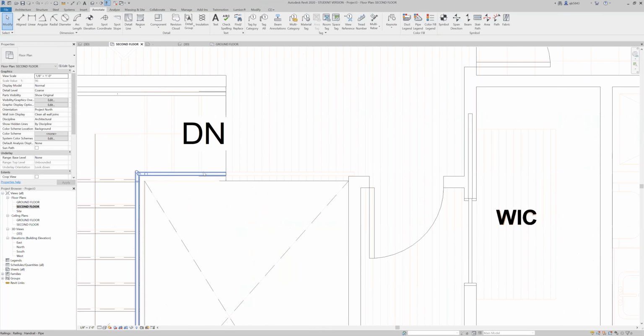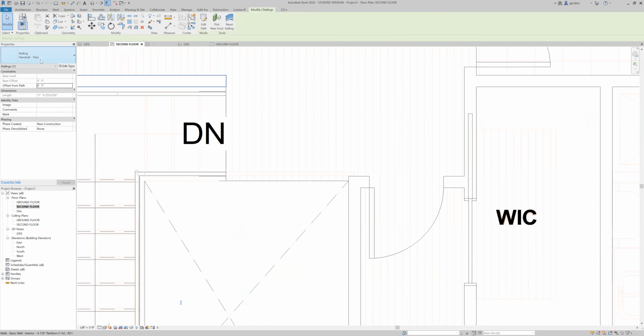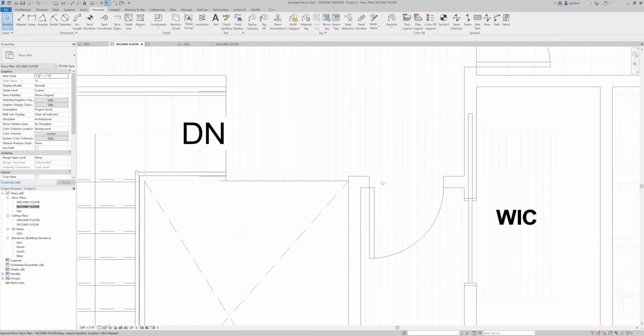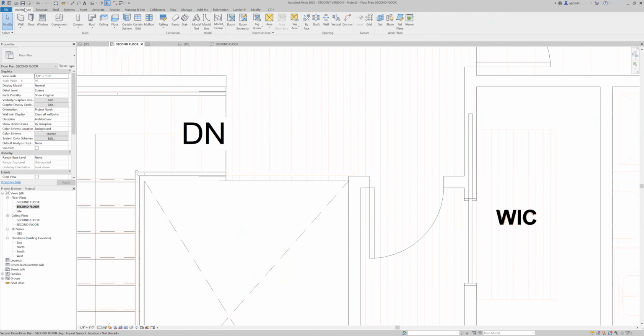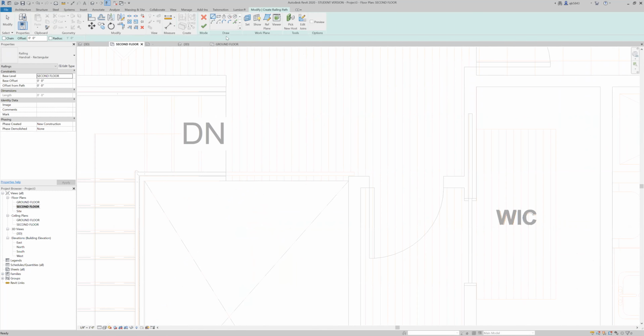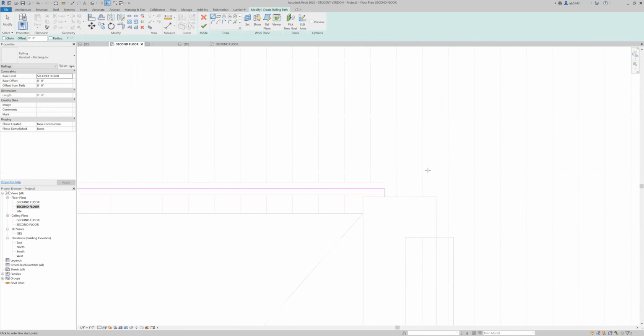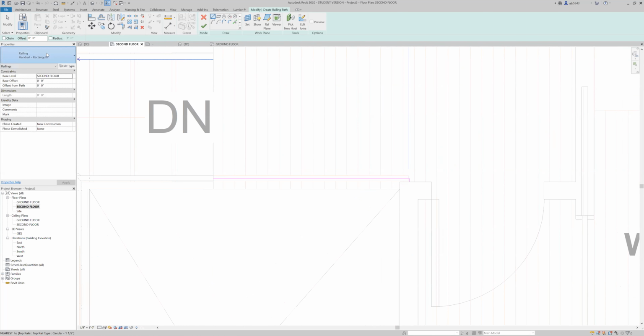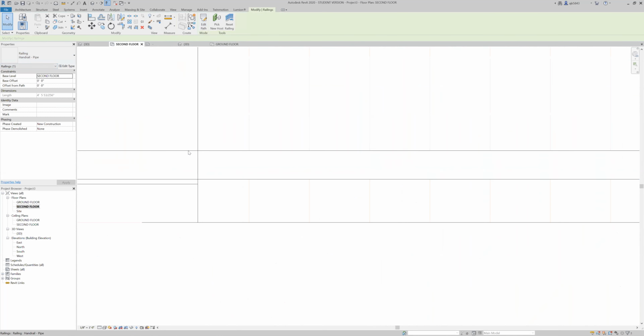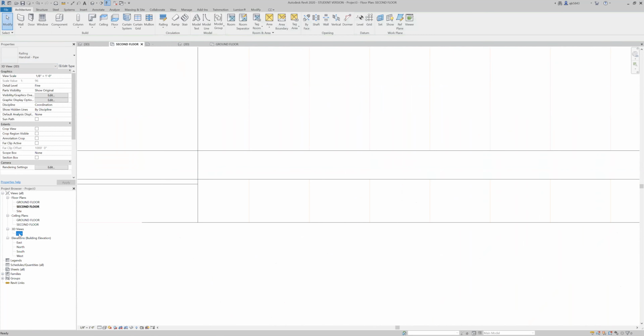And then probably the last thing right here is to continue this pipe handrail. So this could be a solid wall, it could be a railing. For this, we'll use a railing. Railing must be a continuous line. So we'll go ahead and place that in the direct center. And then we'll bring it back into that wall just like that. And we're using the pipe handrail. And we'll hit OK. So then that'll make a new pipe handrail that perfectly lines up with our staircase.